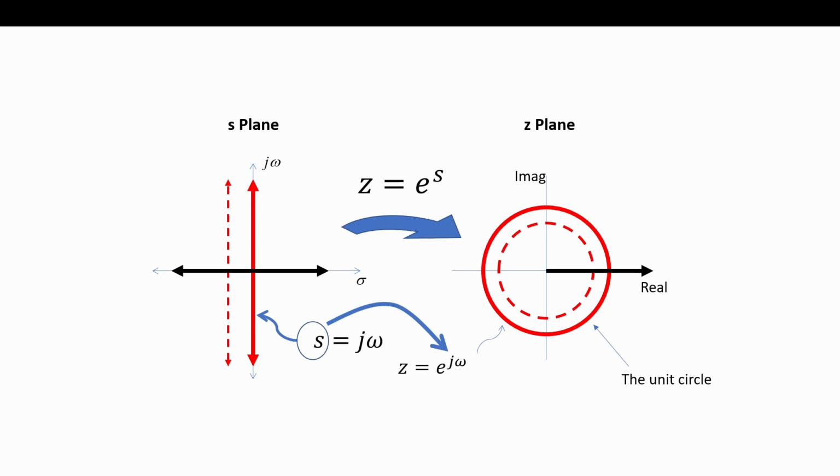So it's a logarithmic scale that you'll see on the real axis. So these grid lines are going. And then finally, this origin where s is 0, if you think of the Fourier transform again, what does that represent? What is the origin as far as the Fourier transform? When I have omega equals 0, DC, right?